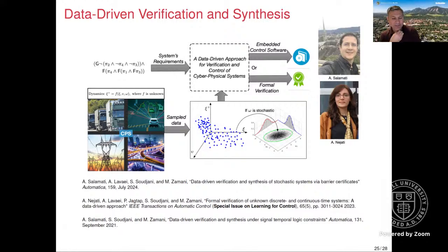One thing you can always do in the offline setting is use those data points that are already given to you to come up with a very rudimentary safe controller. When I say rudimentary, the domain of the controller is very tiny. You can come up with a controller, but it only allows your system to evolve in a very tiny region. So in that case, you at least guarantee that you are safe, but my robot is evolving in a very tiny neighborhood. Now you switch to the online setting. You start exploring and expand the domain of safety, as the robot is collecting more and more data. I think I've seen a lot of work in that direction as well.